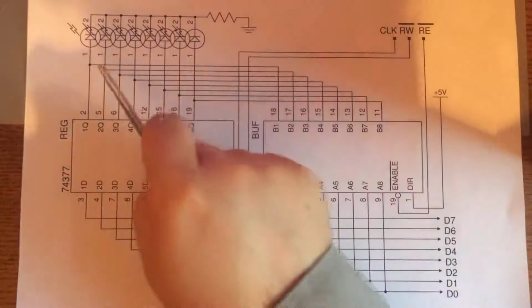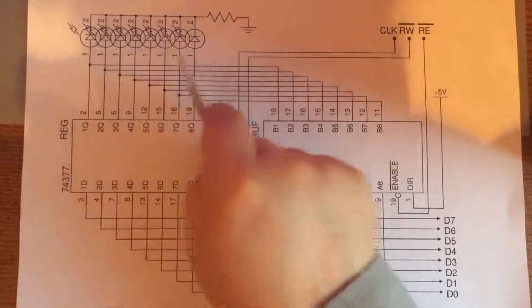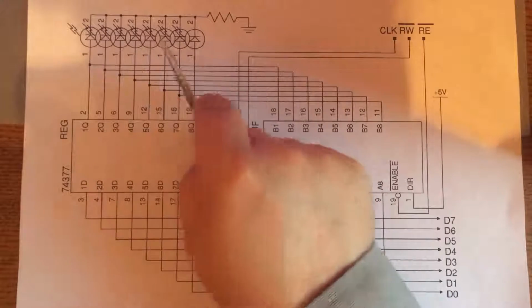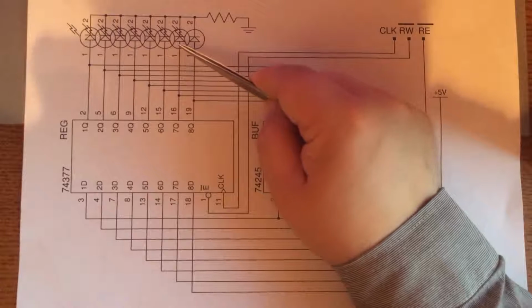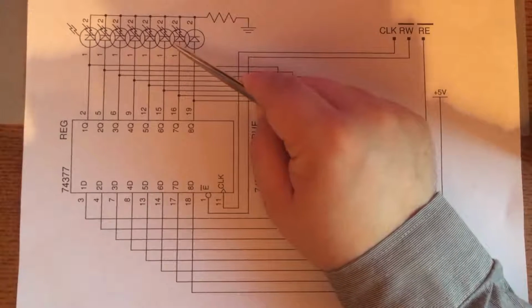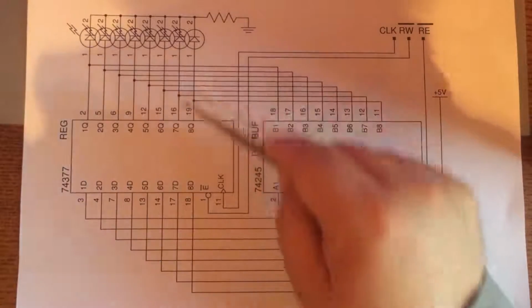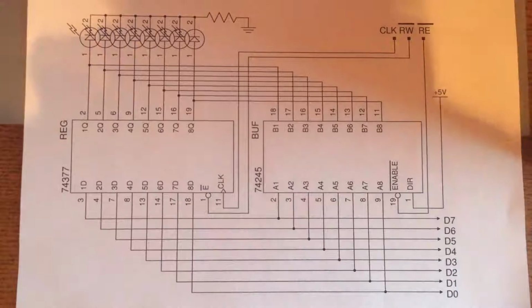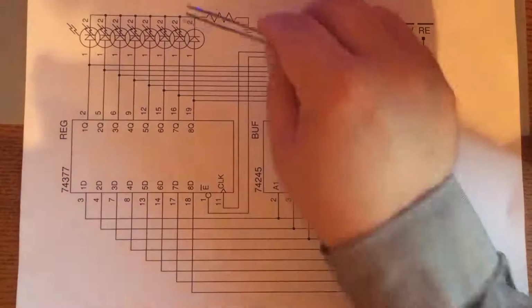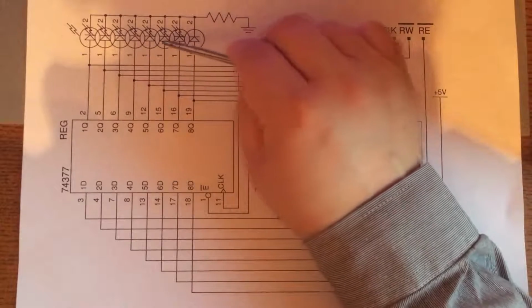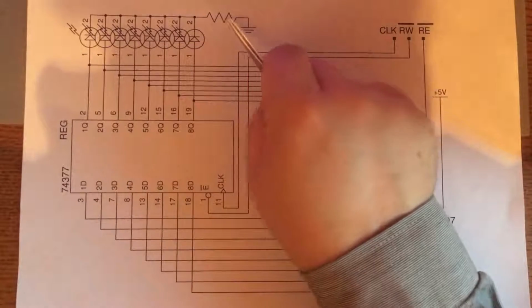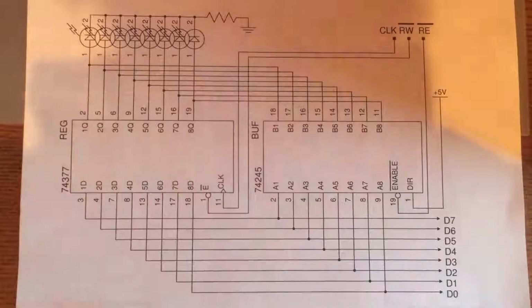And so depending on the value which is being shown, if I have more or fewer LEDs which are showing a 1 state, they will actually change in brightness. And that's a little bit of an odd effect when you look at it the first time. And if I were to rebuild this computer in some future, I would probably use LEDs with built-in resistors, because then I would have a current limiting resistor for each LED individually, and so I wouldn't be sharing a single fixed current value amongst all LEDs.